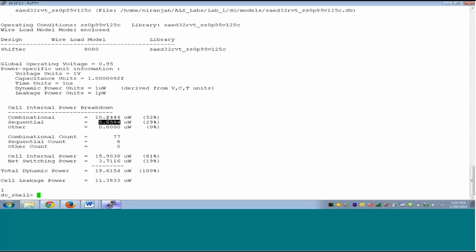So that was all. We saw how to report power. We saw the power compiler clock gating. We spent some time studying the dotlib, how the power number is represented there, and what kind of clock gating cells are available. We inserted clock gating. We saw that even for a smaller design, the dynamic power number does get reduced. We saw the leakage power. We saw the default switching activity that DC uses if we do not give any. So that concludes Unit 4.